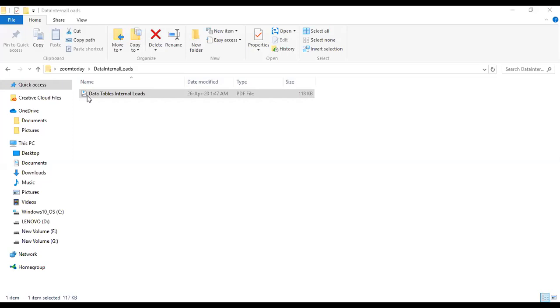Now, this table, the sensible heat cooling load factor, you will also need. It depends on the total number of hours in the space: 2, 4, 6, 8, 16, and this factor will be multiplied with the number of occupants in the formula. Now, let us take another sheet.